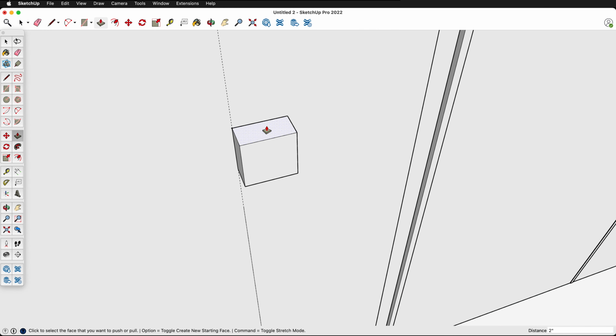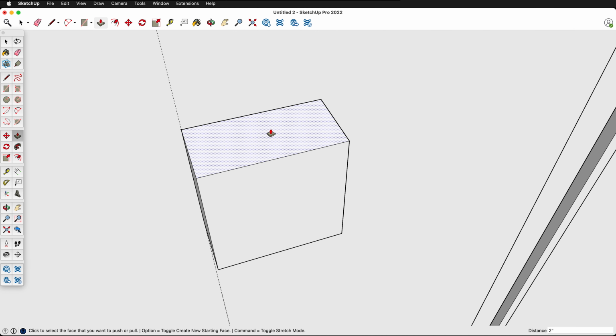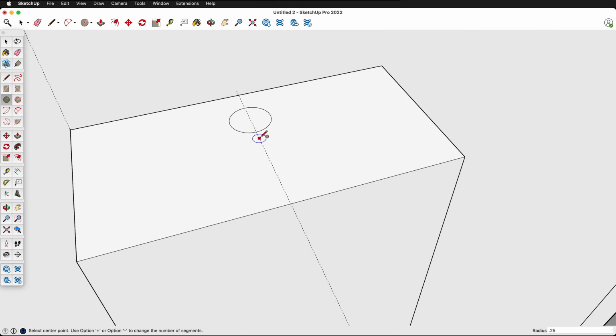And then I could also just go ahead and put in the conduit. With the tape measure, I'll tape over 2 inches. So that's in the middle. And then somewhere right around here, I'll press C, and I'll move this out 0.25 inches. And then I'll press F to just come out here, and I'm going to go 1/8 of an inch.